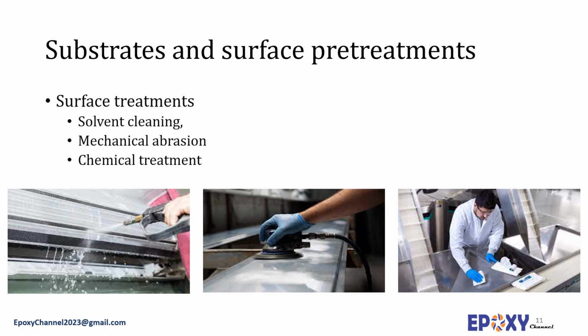Chemicals such as sulfuric acid and hydrofluoric acid can be used for steel alloys, whereas the surface treatment of aluminum alloys can be conducted through chromic sulfuric acid etching or through anodizing techniques. Alkaline hydrogen peroxide etching and a sodium hydroxide anodizing process can be employed for the surface treatment of titanium alloys. There is also the possibility of using primer to enhance the adhesion.